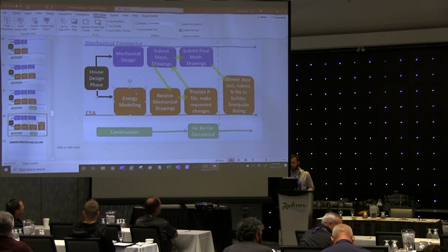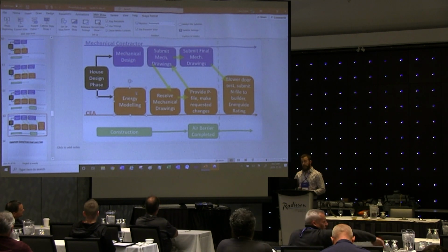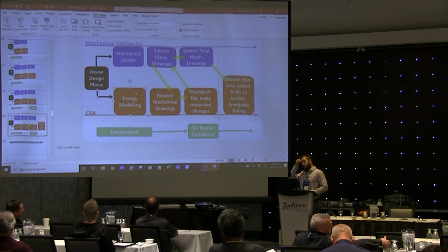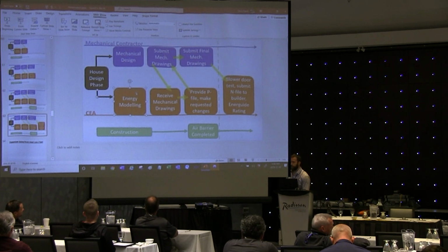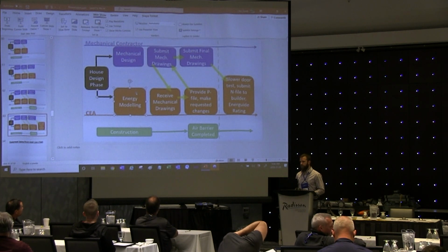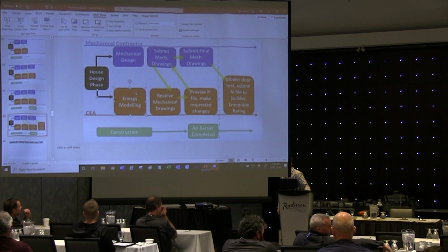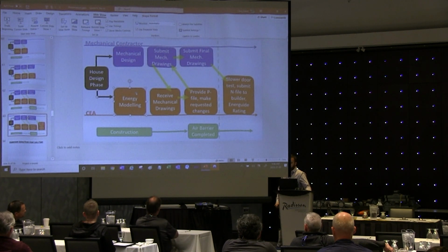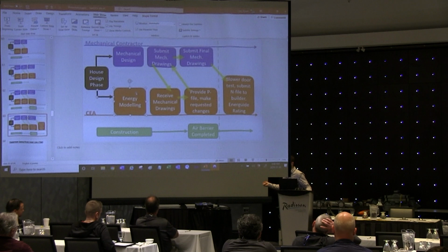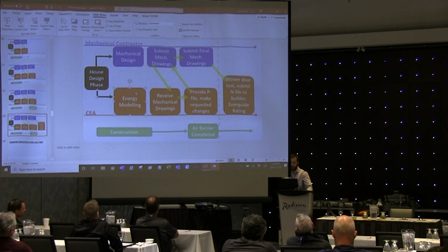Hopefully we're getting blower door tests prior to drywall. Yeah. See, that's huge, right? Because then you can make sure that that mechanical system is ordered based on that average. That system down below was designed for, say, 3.75 air changes per hour. If they're running at 5 or 6 in the house, we bring that down to meet that. The test has got to be before drywall. Exactly. Yeah, there is one earlier as well. Yes. That's the most important one.